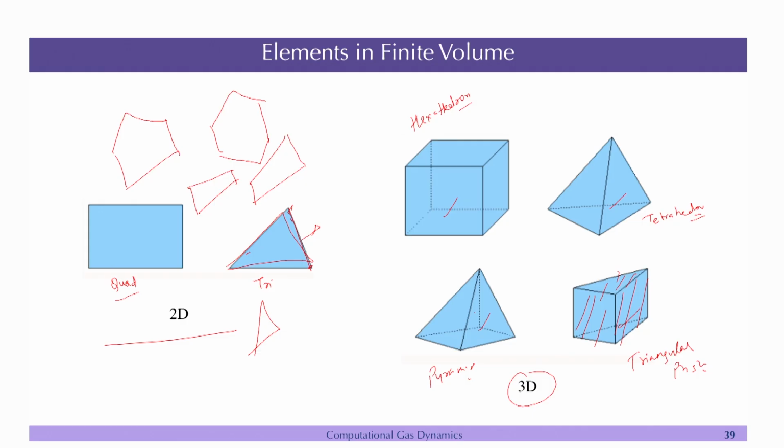As soon as you have the mesh, the solver creates all this information: the centroid of the face, the cell centroid, the area normal direction, the area everywhere, the cell volume. Everything is calculated, because this information is required in every single iteration, and you do not want to calculate it every time. So this is a kind of preprocessor before you start the iteration. It depends purely on the geometry, on the mesh that we have.